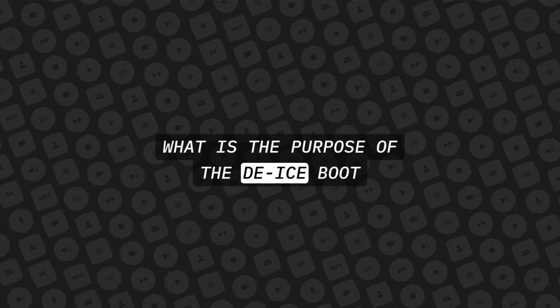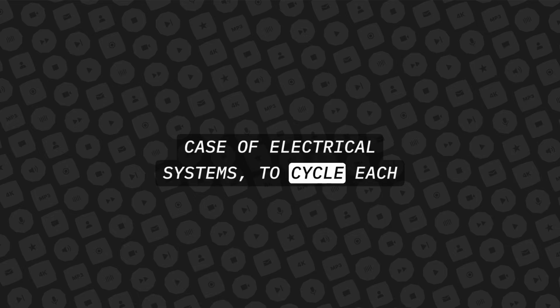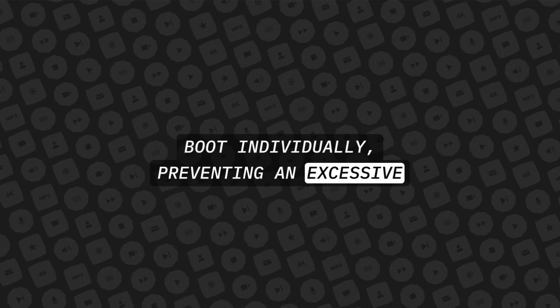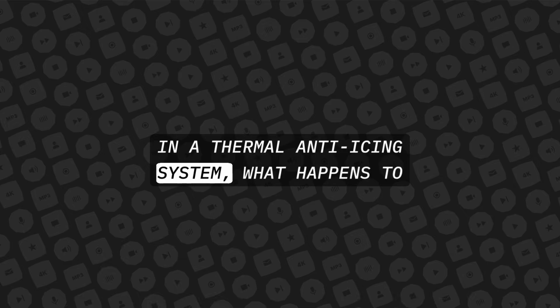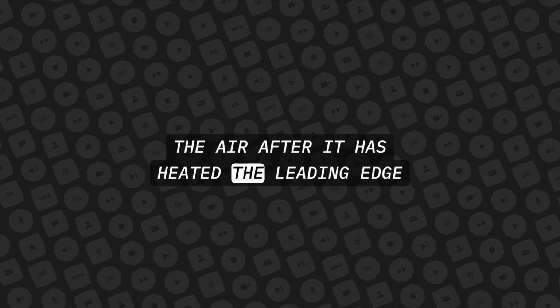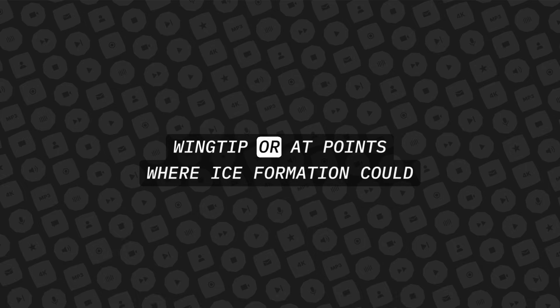What is the purpose of the de-ice boot electrical timers? To inflate the boots symmetrically, or, in the case of electrical systems, to cycle each boot individually, preventing an excessive load on the electrical system. In a thermal anti-icing system, what happens to the air after it has heated the leading edge of the wing? The air is exhausted to the atmosphere at the wingtip or at points where ice formation could be critical.